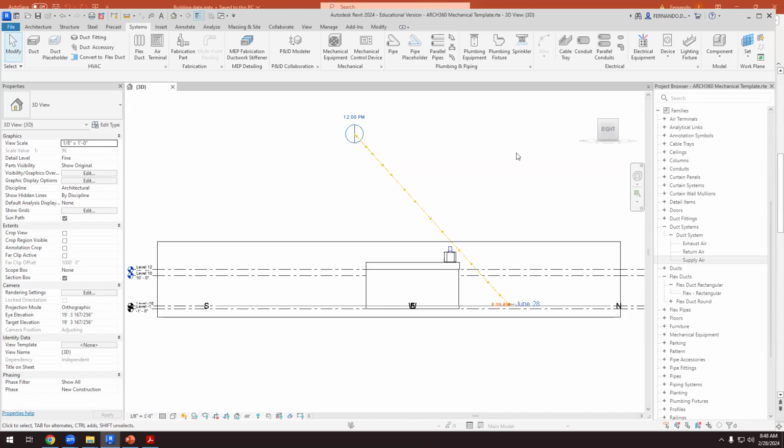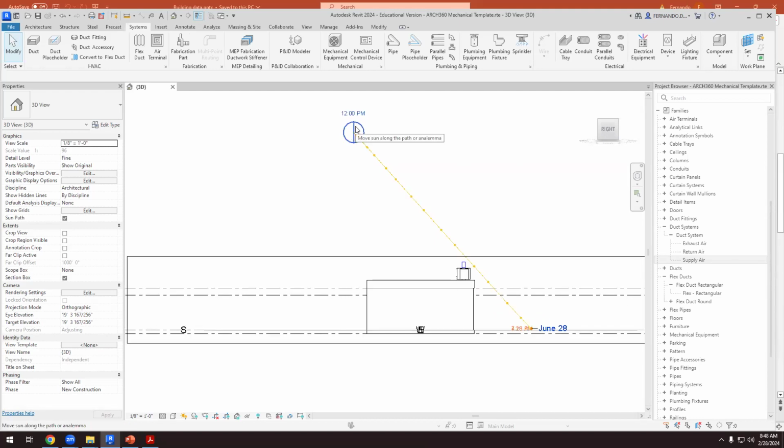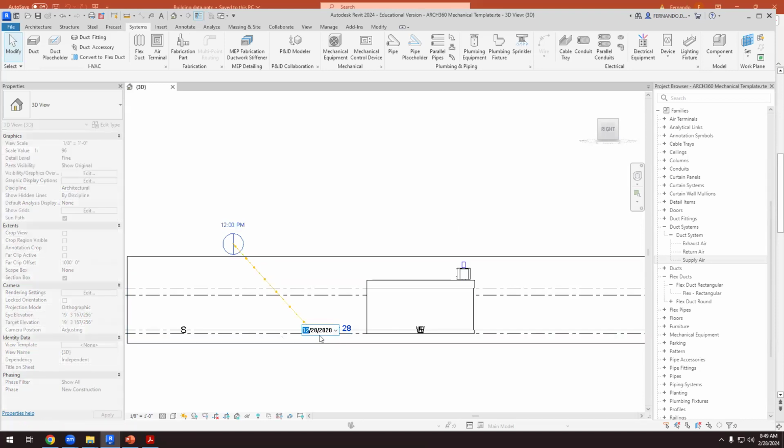So I have to make a decision because I can't change the angle. Well, I can do it, but again, it's very expensive. I can't change the angle of the sun. So the highest position on the horizon is in June, and the lowest position would be in January or in December. It's better in December. Okay, so that's the sun angle. So that means that in December, the panel should be almost vertical. In June, the panel will work well if it's almost horizontal.